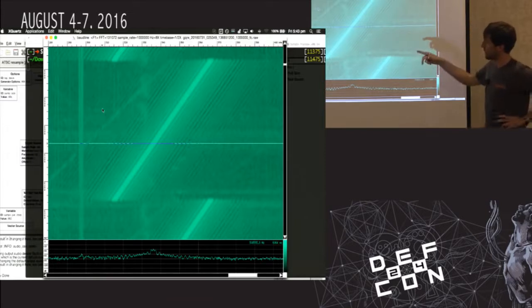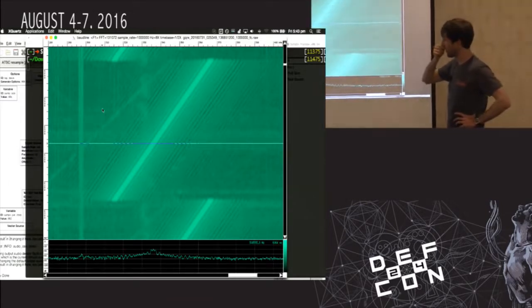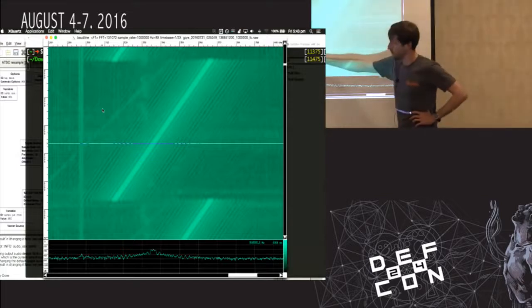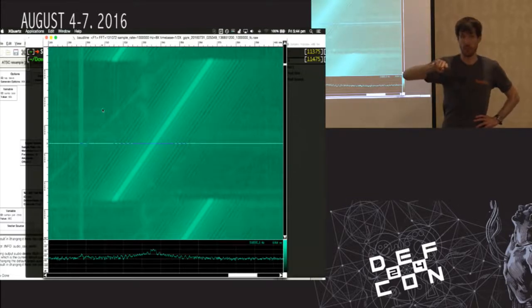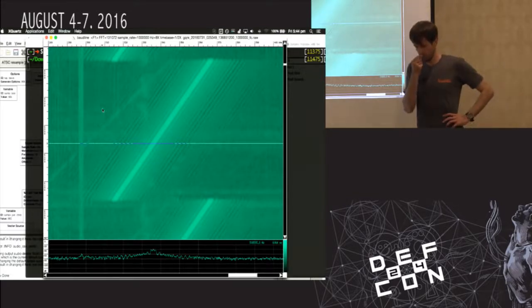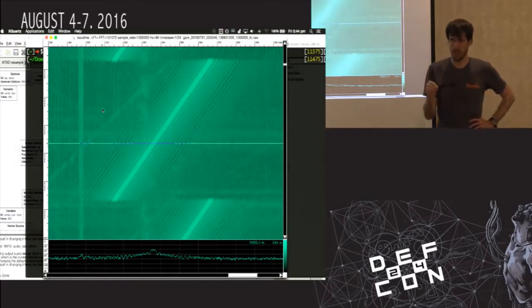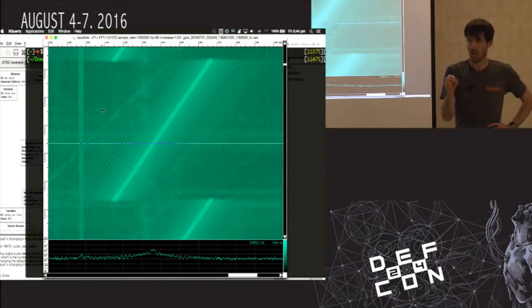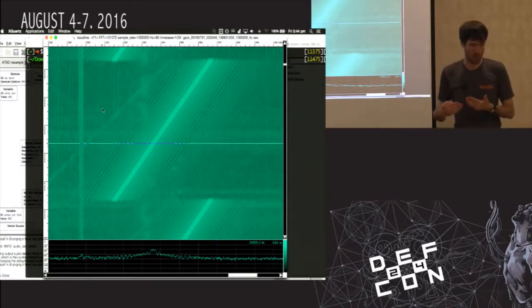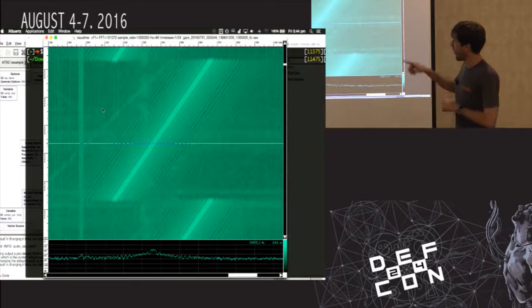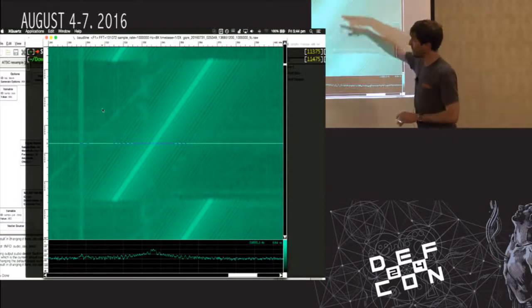And the reason why that turns out, Peter, who does aerospace, actually had this on his blog. Really interesting is that this is actually AMing of the signal due to the fact that the transmitted signal is gated, which means that they're not transmitting continuously. They transmit a little burst, and then they stop the transmitter, switch to receive mode, listen, and then switch back to the transmitter, which is what, for example, the primary surveillance radar does at an airport. And that makes sense because they're using the same antenna to transmit and receive. So that's what's producing this AMing effect in the frequency domain.